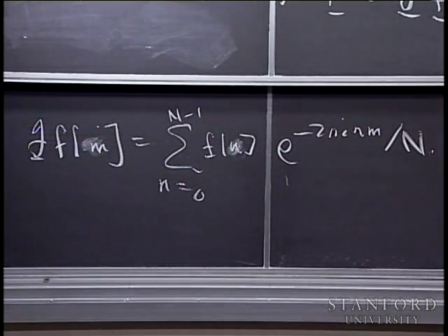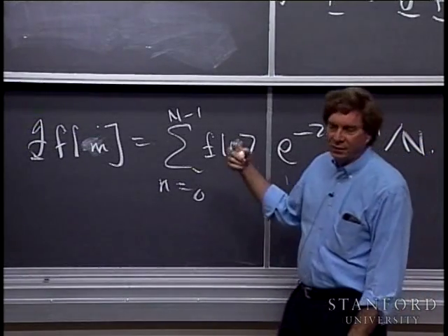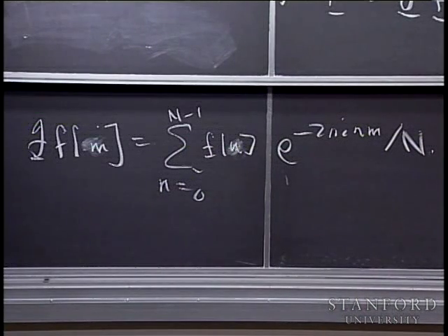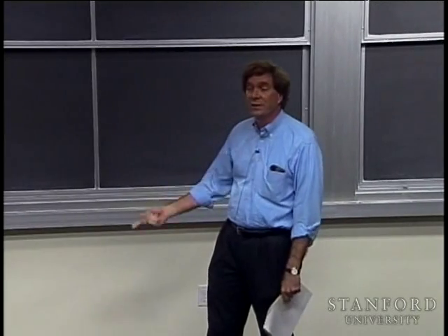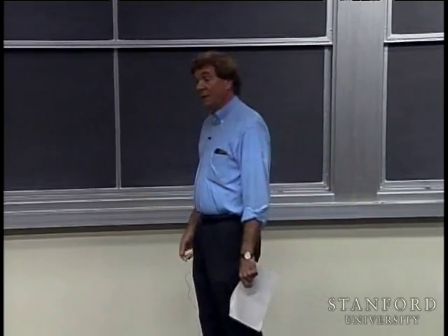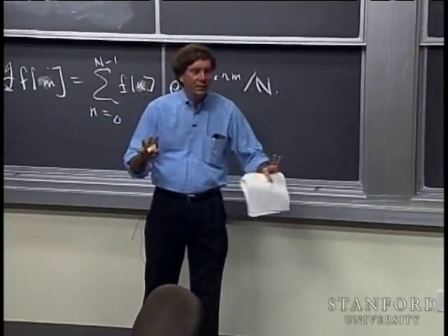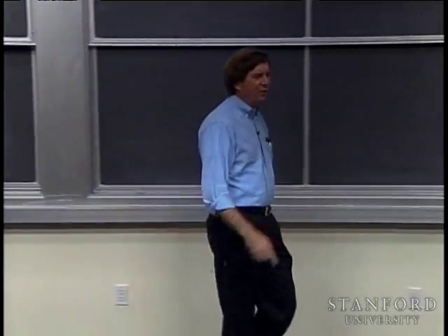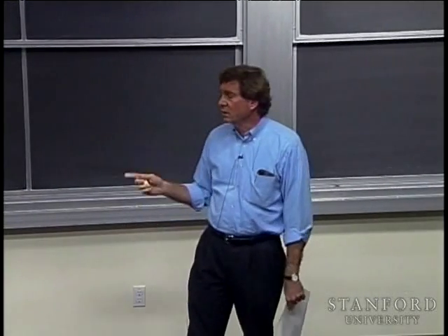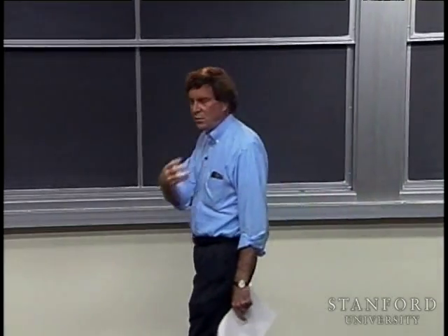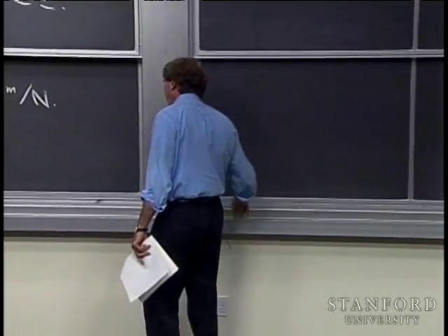And you don't see at all the fact that in our derivation, this came from starting with a continuous signal, sampling it, sampling the Fourier transform, and then somehow ultimately leading to this definition. Here it's just an operation on discrete signals, one discrete signal producing another discrete signal. And that's pretty much how we're going to deal with it. All right, but before embarking on that path forever, I want to have one nod back to the continuous case, and talk a little bit about how the DFT is employed and the kind of things you have to know when you're going to use it in practice, as you already have to some extent, and you certainly will more in the future.